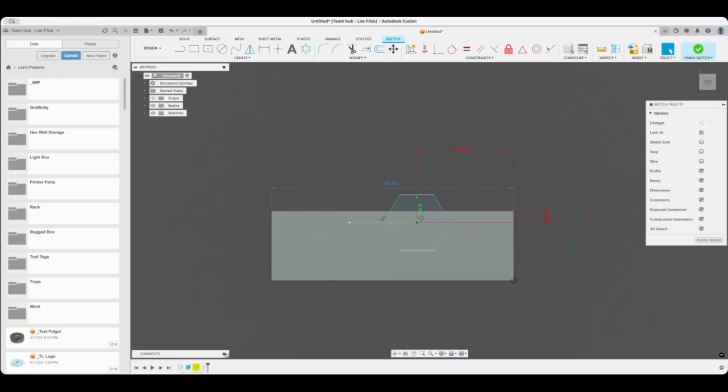So go to your second sketch, change your 40 to 50 and your 25 to 15. Now, if you get the two red dimensions like I have here, it's because we locked that line. So to unlock it, you just click the lock again and then click the line. Yes, I did that.